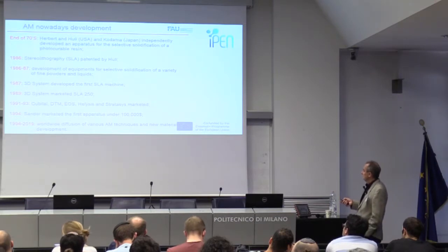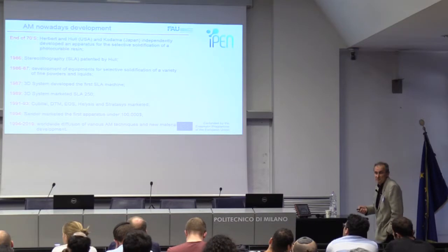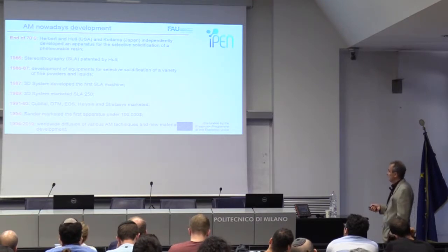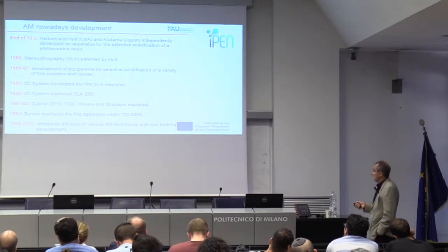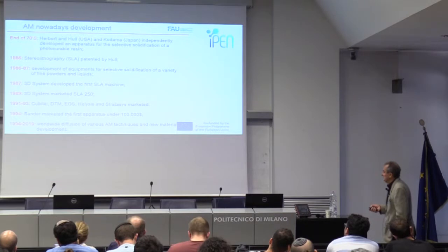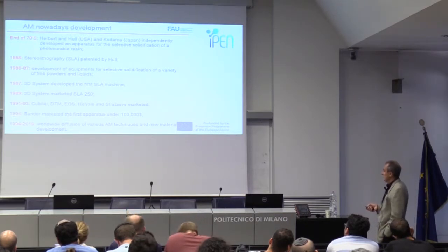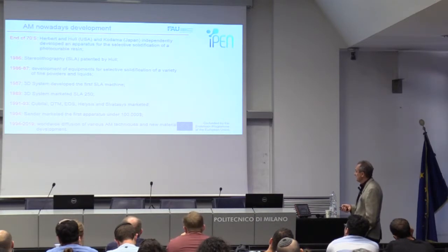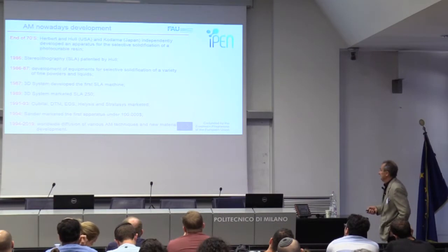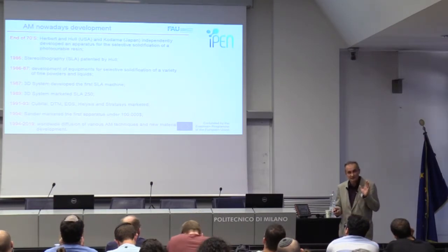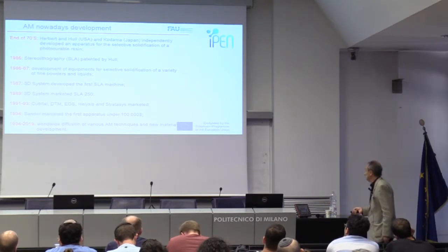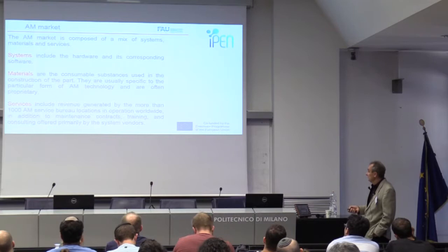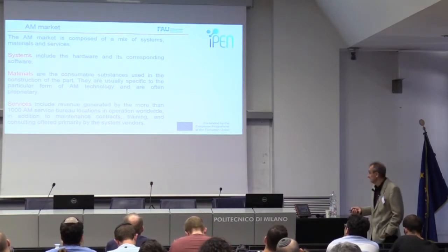And stereolithography was patented in 1986. It's only 33 years ago. It's new. And after that, 1 year later, 3D Systems made the first SLA machine. It was developed. In the 90s, you have the apparatus shown at around 4,000 dollars. Really on the market, and just now there is nearly a new explosion of this technique and diffusion of various additive manufacturing technology, as I mentioned, in different fields of science and industry. What is the market? If you are a manager, you should think about systems, material, and service. Of course, just now there really is service.